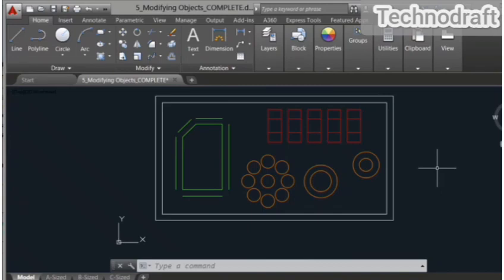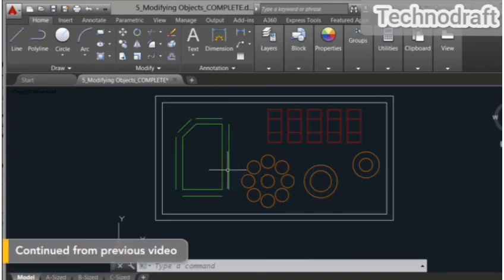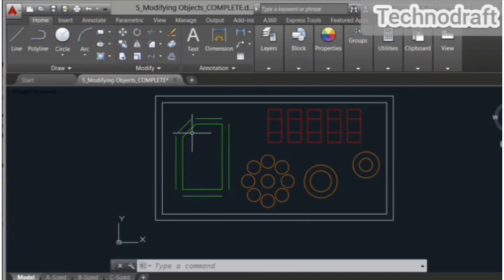You may remember in one of the previous parts when we used the offset command, we offset these green lines of our little control panel, our operation panel. Here it is, so there is our little control panel. What you may have here is a little screen readout, maybe a little keyboard to press some buttons. Now what we did was we offset all of these lines, but we didn't tidy up the corners. We are going to utilize the AutoCAD chamfer and fillet commands to do that, and the way that we are going to do that is by utilizing the radius setting in the fillet command to give us some nice clean corners.